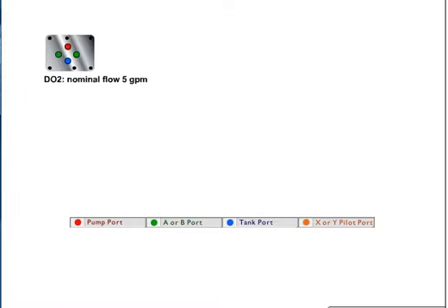The spool-type directional control valves in industrial applications are subplate or manifold mounted. The porting system is industry standard and designed by valve size. Directional control valve sizing is according to flow capacity, which is critical to the proper function of the valve. Flow capacity of a valve is determined by the port sizes and the pressure drop across the valve.